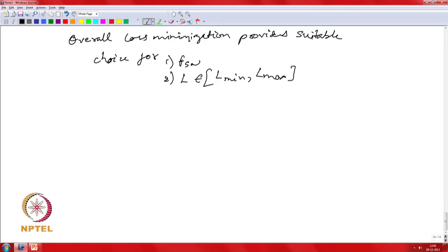So, at this point we now have your selection of L1, L2, C, and we can look at non-idealities of your power converter. A primary non-ideality which you automatically get once you go into a higher order filter design is how to deal with filter resonances. So, this is one aspect that we would need to consider.